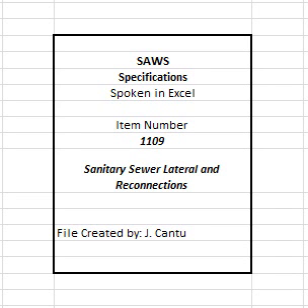2. Preparation. A. Determine the existing sewer lateral locations and number of existing service connections from closed-circuit television, CCTV, inspection video or from a field survey. B. Accurately field locate existing lateral connections, whether in service or not. C. Use existing lateral locations to connect or reconnect service lines to the main.